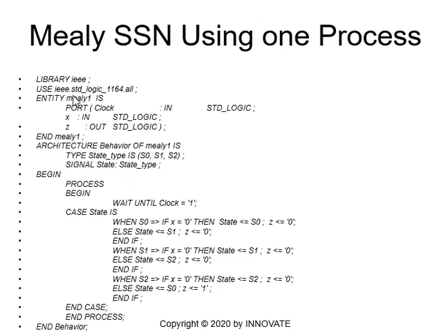Library IEEE, use IEEE standard logic 1164, entity Mealy 1 is port. I will define clock as an input, X also as an input. I can add clock, comma, X if I want to, Z as an output in standard logic. In Mealy 1, architecture behavior of Mealy 1 is, I will declare state type, which is the states that I have: S0, S1, and S2. I have 3 states.